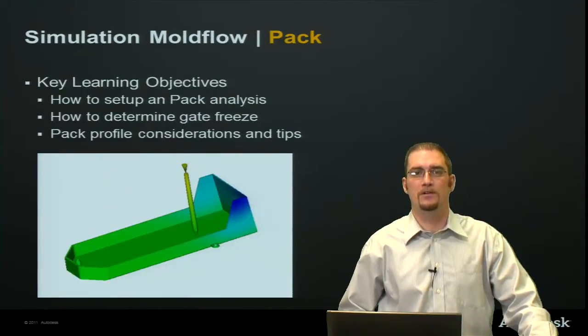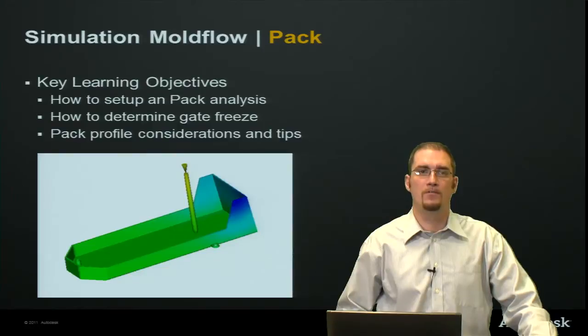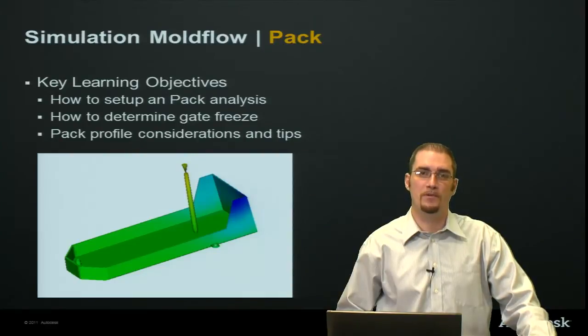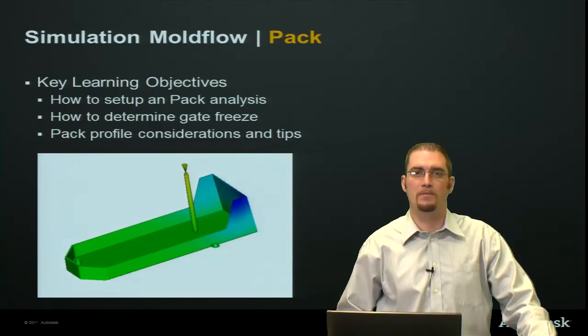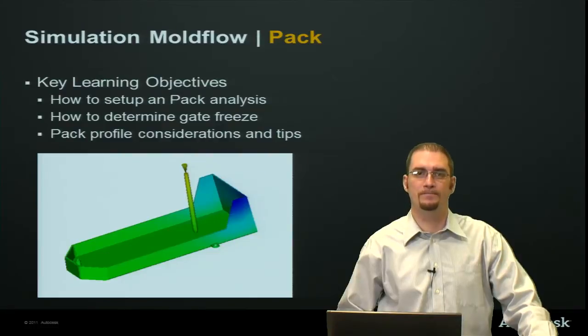So some key learning objectives that we'll go over will be how to set up a packing analysis first of all, how to determine gate freeze once you have your pack results, and then some pack profile considerations and tips to help you get started with optimizing your profile here.